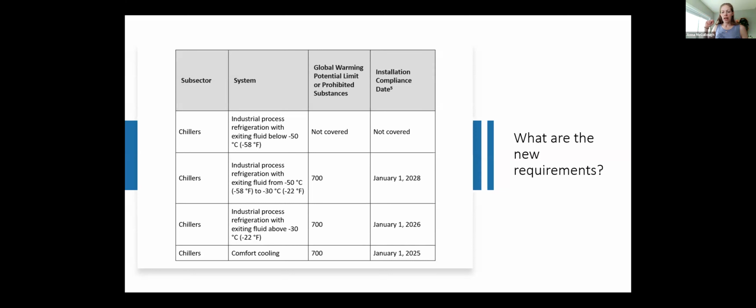Then, if you have that safety shutoff valve, the calculation can be completed to determine if the charge within that refrigerant line set and evaporator in the plenum space is greater than the allowable LFL. If it is, then you have to provide the detection and ventilation.